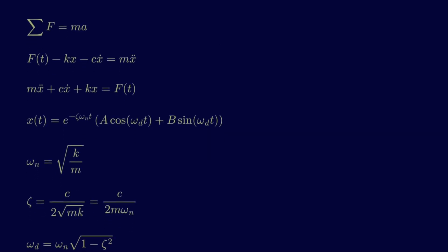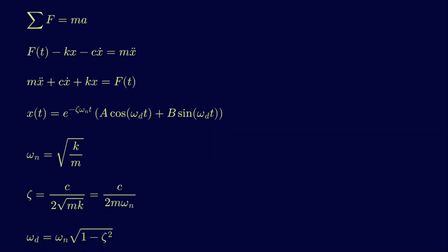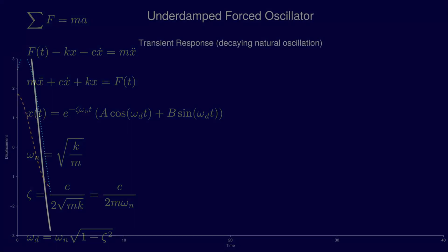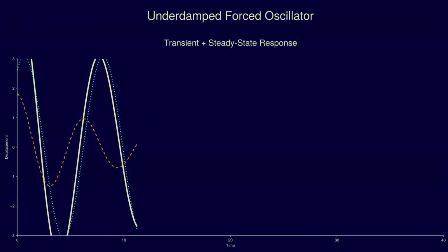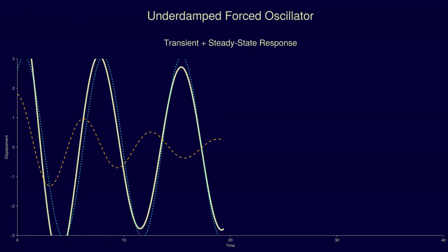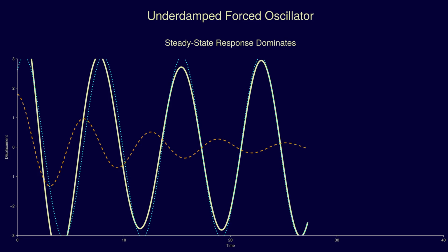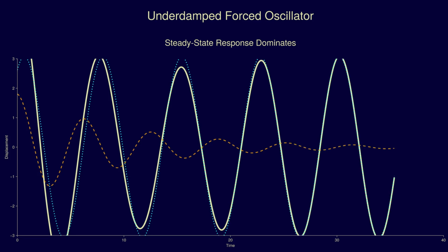The spring mass damper system is foundational to control systems. By analogizing a complex system and reducing it to simple harmonic oscillation, we can get an insight about the system's behavior and how far away it is from our desired behavior. By adjusting the natural frequency, we can make a system respond faster or slower depending on the application.